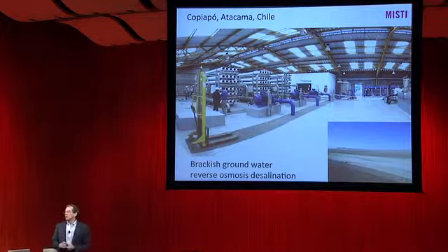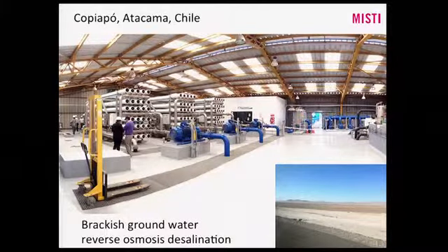What's going on? Well, desalination plants of this sort are using membranes. The membranes are impermeable to salt, but water can pass through. And what's done is to pressurize saline water on one side of the membrane. That forces water through to the pure side, overcoming what would otherwise be the osmotic tendency for water to go from the pure side to the saline side in a quest for equilibrium. And in this particular case, the pumping is being done by the pumps you see in the foreground. These are running about 9 bar, 9 atmospheres, given the relatively modest salinity of the water.